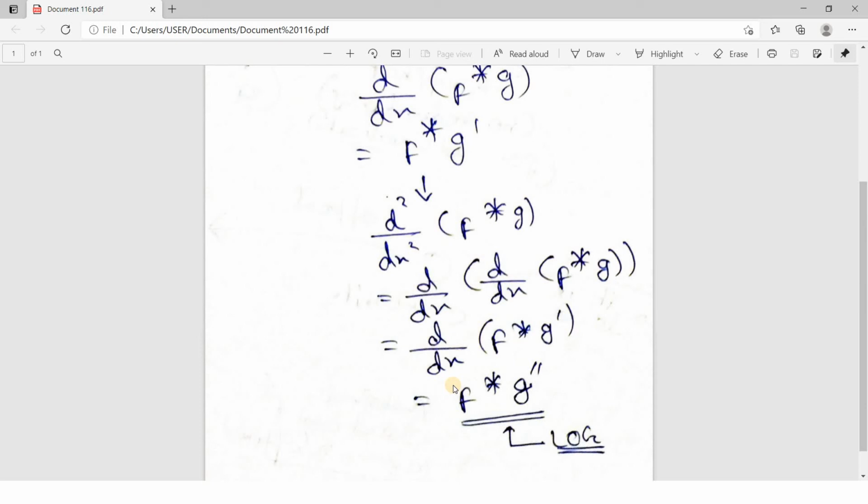Now to make the whole process more resource efficient and less time consuming, instead of applying the double derivative on the low pass filtered signal, we take our original signal and convolve it with the double derivative of our Gaussian kernel, and that is the Laplacian of Gaussian, which we do practically. So this is all about Laplacian of Gaussian.